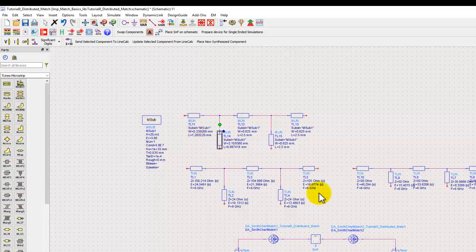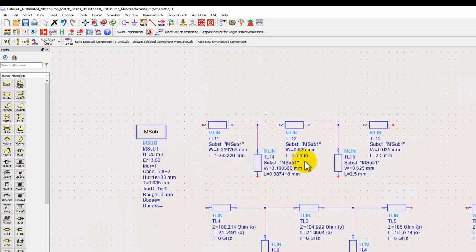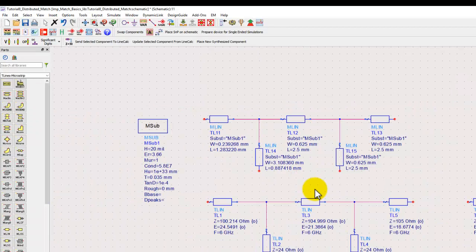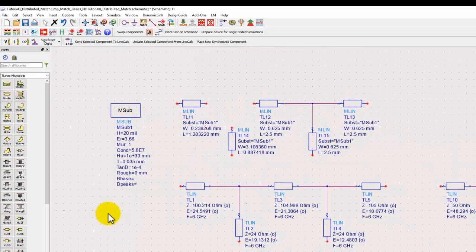After that is done, remember, here's practical tip number 4. If I have this kind of microstrip line and I connect this, I simulate like this, you are missing some effects here. And the effect which you are missing is basically this junction discontinuity. And in RF microwave, the junction discontinuity is the main thing which you need to take care of.